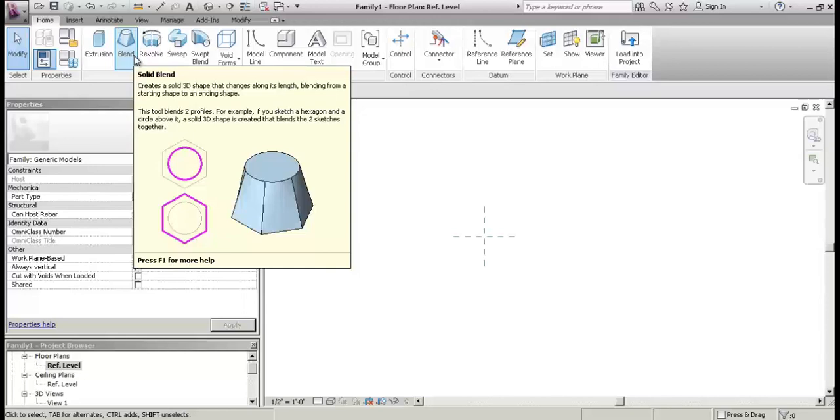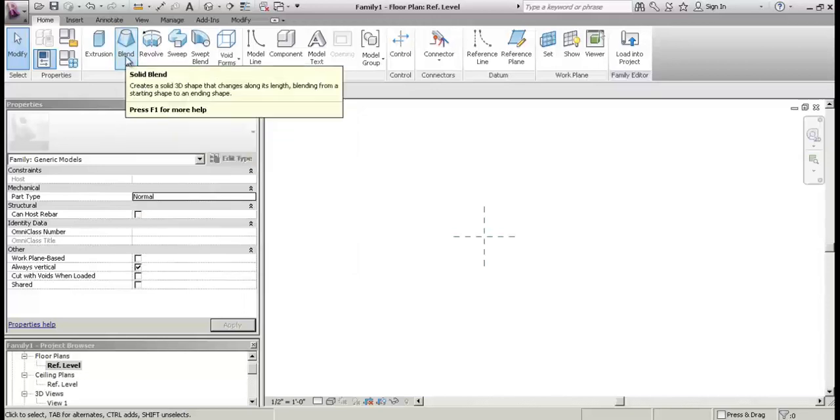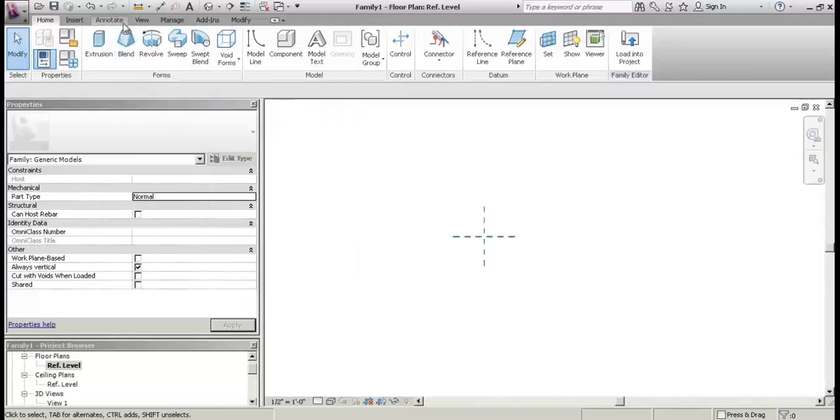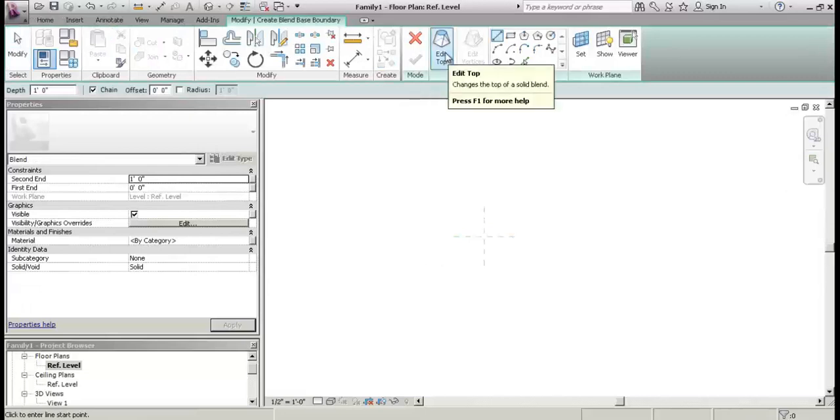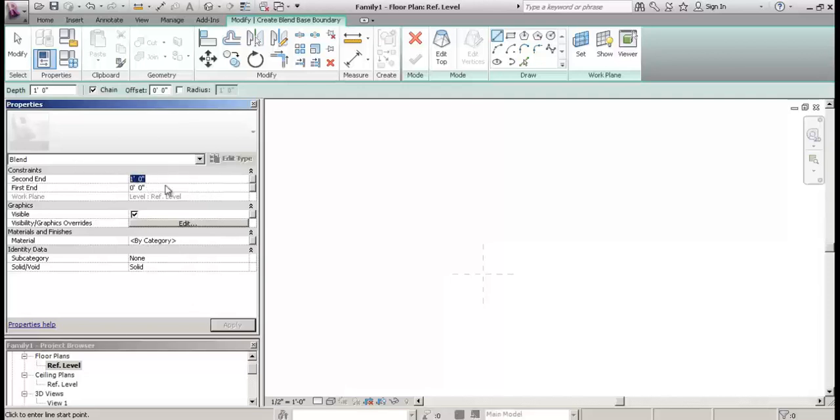So what that piece does here is I can make a bottom part and then a top part and then adjust those dynamically. I immediately enter into the base command, and from the properties window you can either adjust it graphically using the handles as we did in the last case, or I can do this ahead of time and adjust how far up it goes.